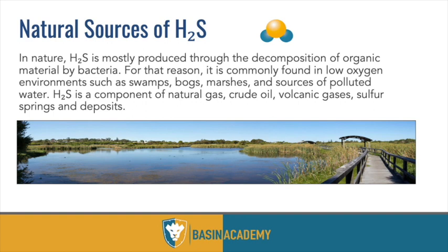Natural sources of H2S, again, it's everywhere, so it's in a lot of places. It can be in swamps, it can be anywhere where you have water that is stagnant, when you have time and opportunity for hydrogen to bond with sulfur without a lot of oxygen, and that's a key factor in the bonding, is that there's not a lot of oxygen. So underground, where we typically find hydrogen sulfide, you're going to see less oxygen in those environments. Typically super salty brines as well that have less oxygen in them, you're going to have more H2S.